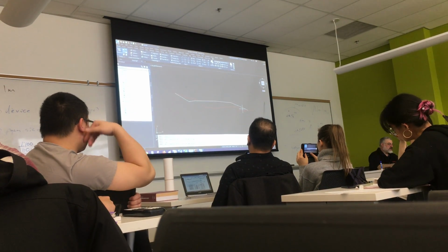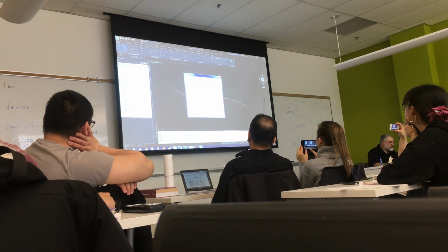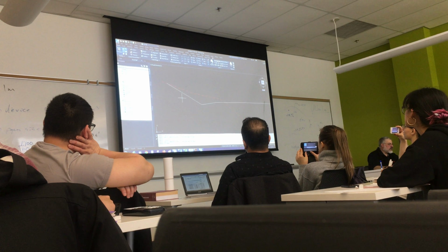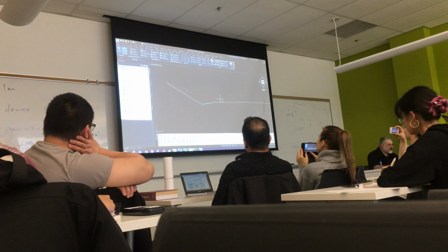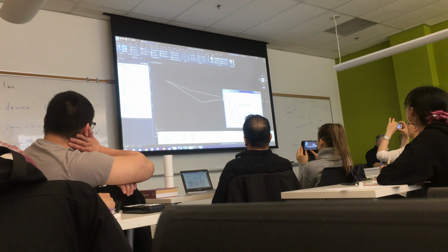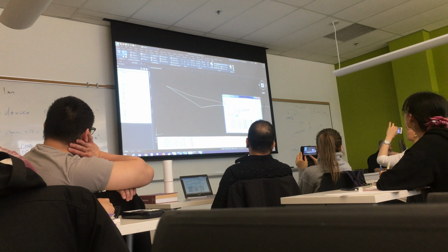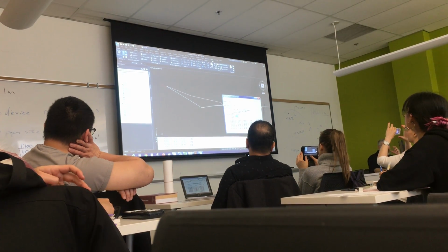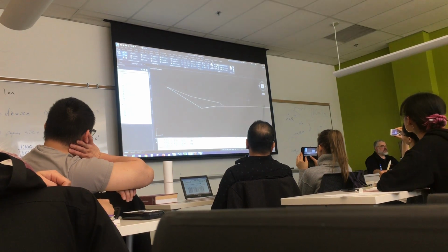Everybody see that? To get the end areas, I turn my O snaps to intersection, and I'm going to draw the line. Polyline from here to here to here to here to here to here and to here. That's the area, right? Because it's a polyline, if I list it, it gives me the length, the perimeter, and the area. So there's the end area, 8.543 square meters. Everybody see that? So that's one method. Trace it with a polyline.